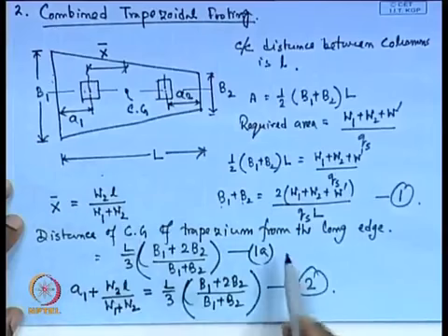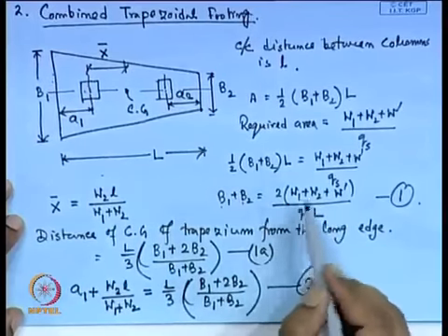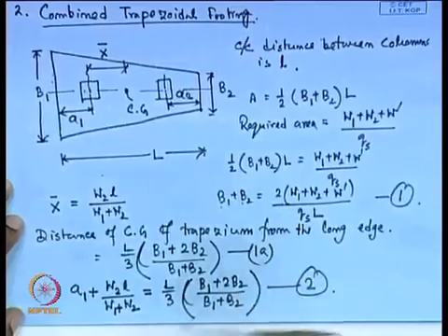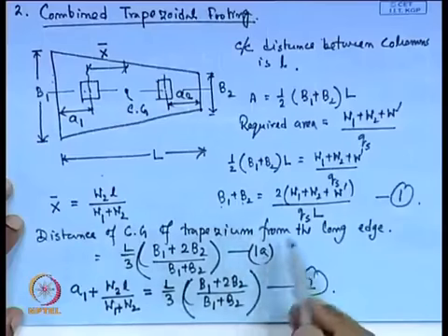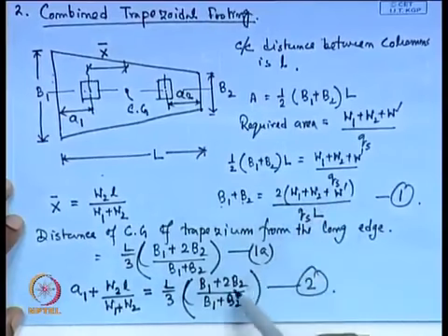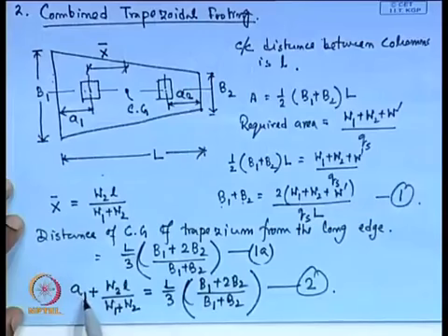So, now we have to first assume suitable values for a few unknowns, then we can choose our dimension of the footing. So, here if we want to find this a1 value, then you have to choose, say, B1, B2 or L, because we have only two expressions, but the number of unknowns are 1, 2, 3 and 1 is here, that is 4.